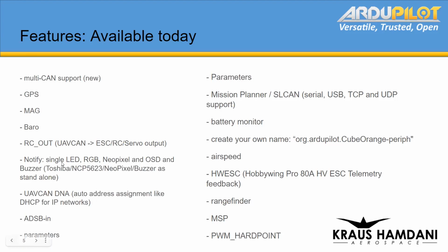One of the earlier features we added was LED and buzzer type support. Toshiba and NCP and NeoPixel, and buzzers, those were added so you can do them individually and it'll fit in the 128K. But if you add any other features, it fills up your 128K. So adding the notify library is the proper way. It takes up more memory, so it doesn't fit in the 128K. But doing that, you basically have all the features in the notify library. That includes your on-screen display stuff, whatever LEDs and NeoPixels and RGBs all at the same time, and buzzers.